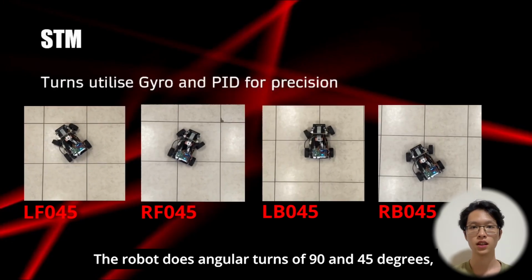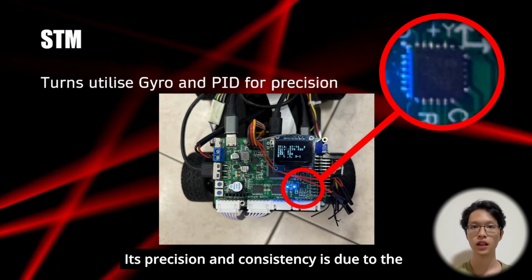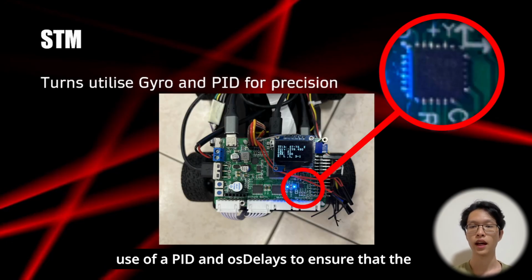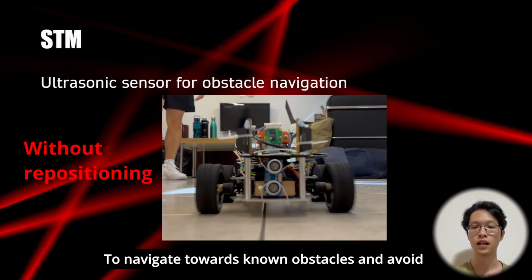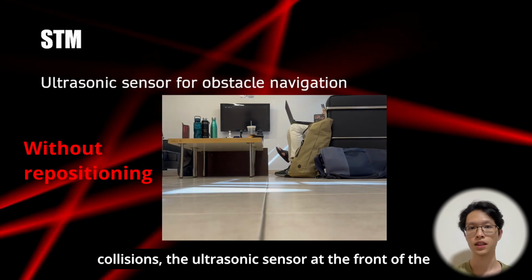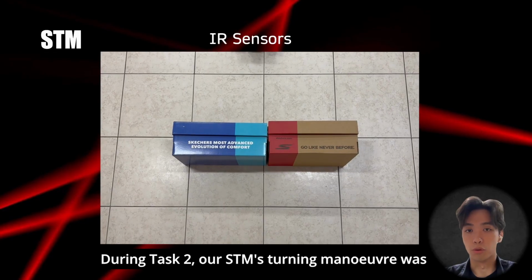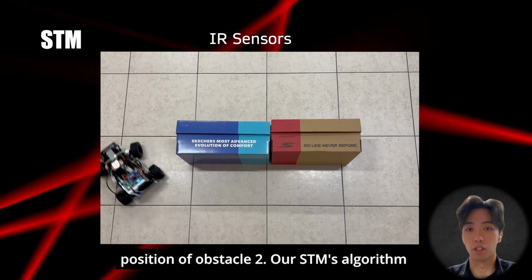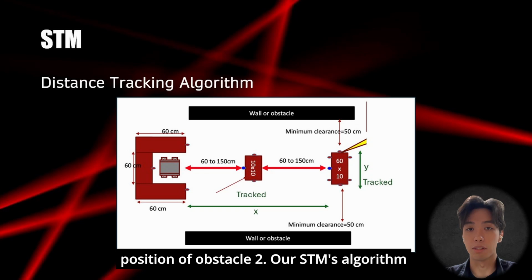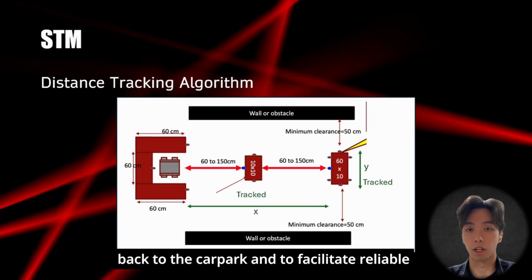The robot does angular turns of 90 and 45 degrees, utilizing the gyroscope on board the STM. Its precision and consistency is due to the use of a PID and OS delays to ensure that the servo motor turns to the correct position. To navigate towards known obstacles and avoid collisions, the ultrasonic sensor at the front of the robot helps determine its relative location. During task 2, our STM's turning maneuver was initiated by IR sensors that identified the end position of obstacle 2. Our STM's algorithm tracked linear displacement during task 2 by monitoring encoder values. This allowed us to precisely calculate the navigation back to the car park.